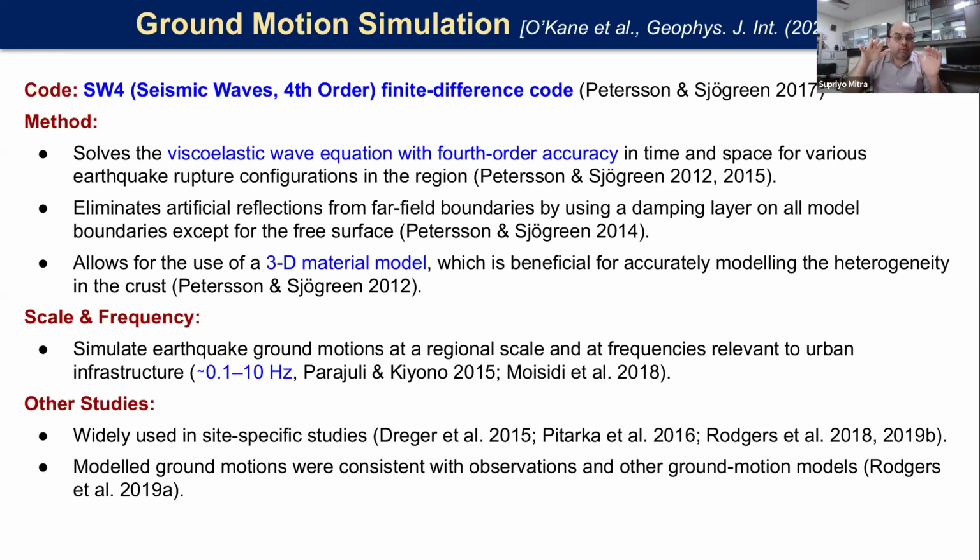And then we look at what the ground velocities would be at the surface. Obviously, when you are looking at the ground velocities within the Himalayas, they are on a different velocity structure than when you are looking at it in the foreland basin. But we do not have the near surface effects in it, if that's the question that you're asking. No, we are not looking at local site effects at all. Okay. So this is all on bedrock level. Okay, thanks.